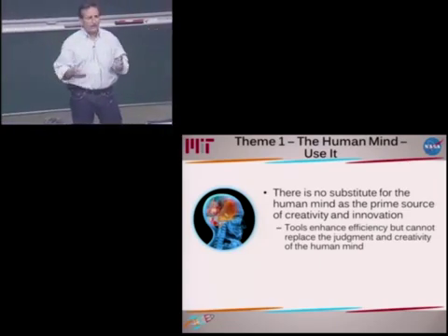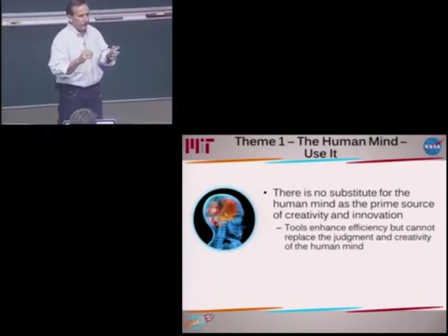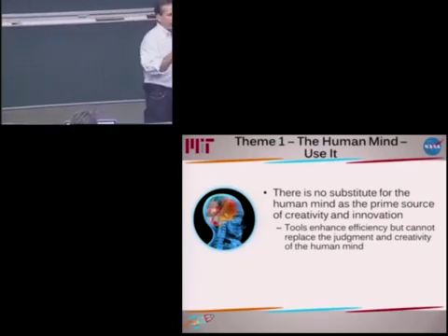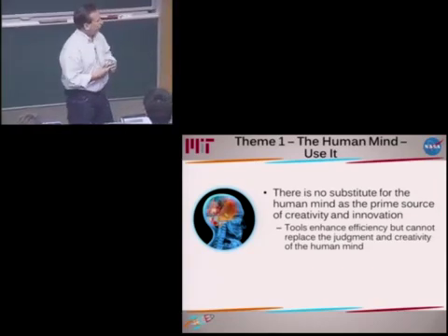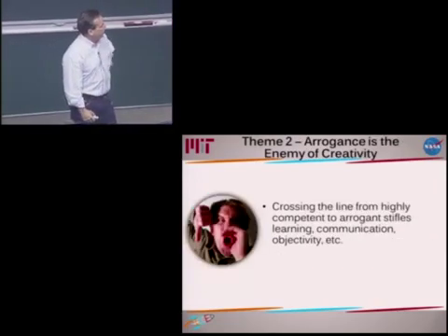We have these great computers. They give us an answer. And especially the younger students tend to believe that that's the truth. Do a back of the envelope, okay? If you're a structural mechanics person, you do your beam theory, and you say, are we in the ballpark? Is this close to being correct? Never trust your first instinct to trust the computer.